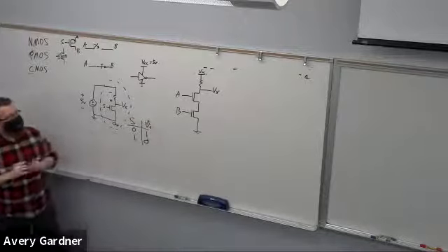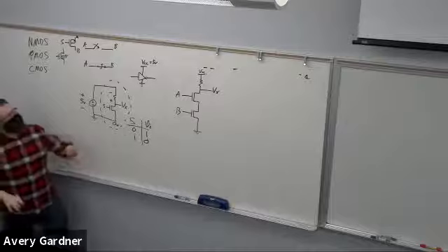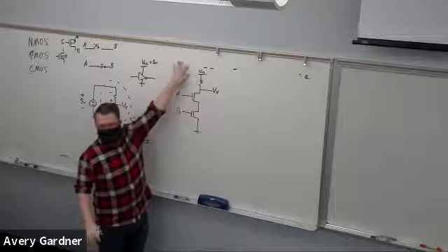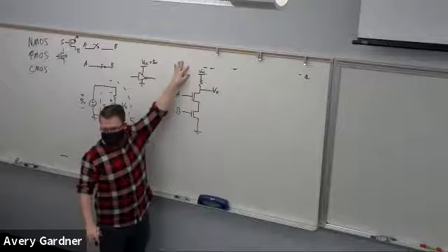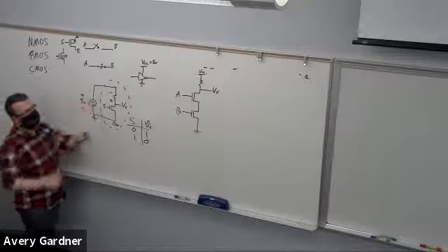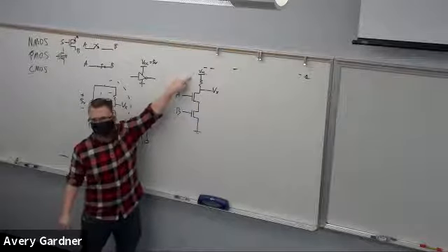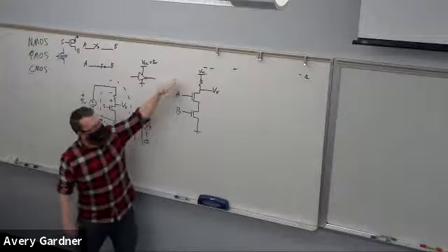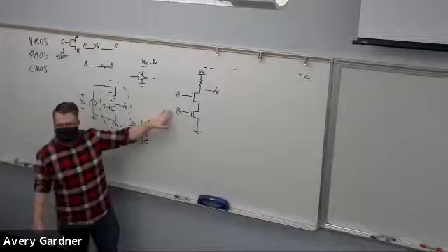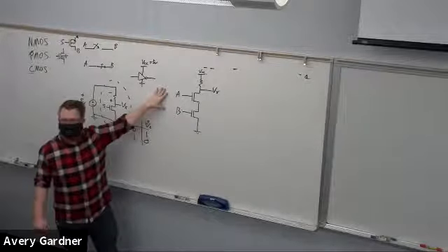Okay, this is a slightly different way to draw essentially the same thing. This VCC, this line with a bar across the top, is a supply or a rail. We talked a little bit about that. It's the same as replacing this part of the circuit with VCC. There's a voltage somewhere providing it to this node, and it can drop to ground. Now, knowing that A and B are both NMOS-style switches, what is this circuit doing?